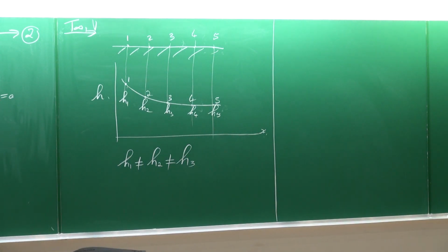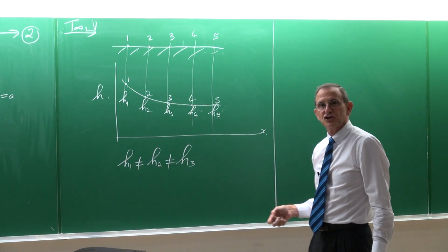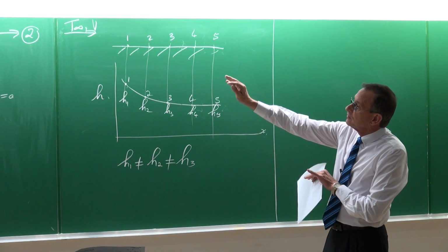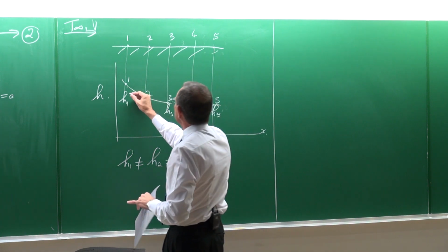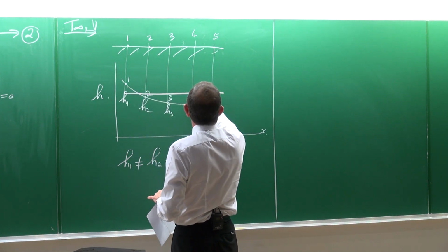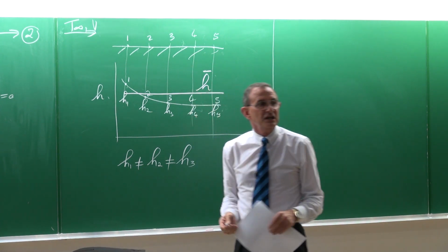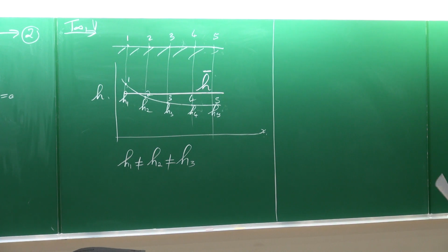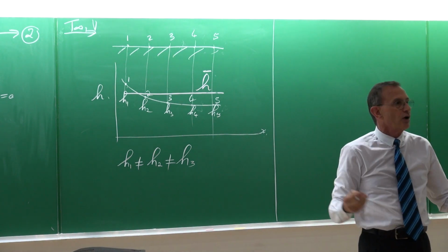But what we do is, if we do those experiments and determine all these heat transfer coefficients, then for a specific body and for very specific conditions, we would of course determine the average heat transfer coefficient. So most of the heat transfer coefficients that you get in textbooks or tables, etc., are actually the average value, which is just convenient for design purposes.